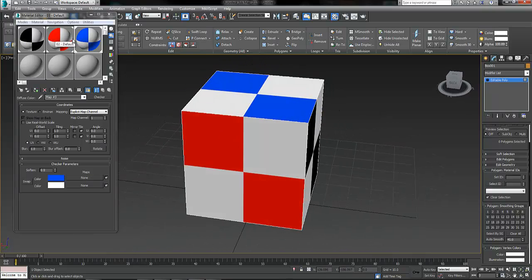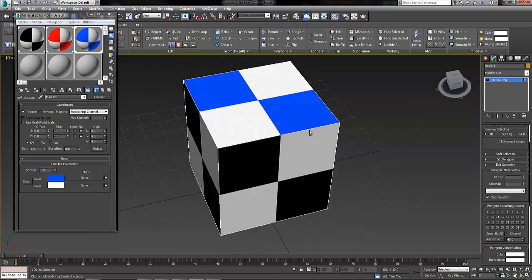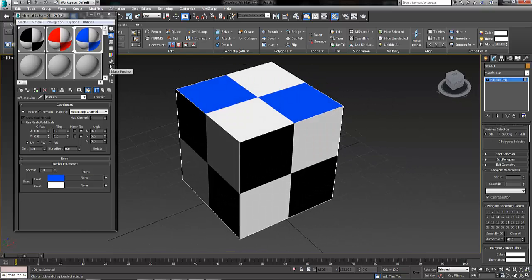And this is very, like I said, important that you put these in order, because not only is it easier to do in 3ds Max, but it also makes more sense. It's like if you're doing modular assets and you have like a brick wall with trim on it, you can set on all your wall pieces, what the actual wall part is as ID 1, and then the trim can be set as ID 2.